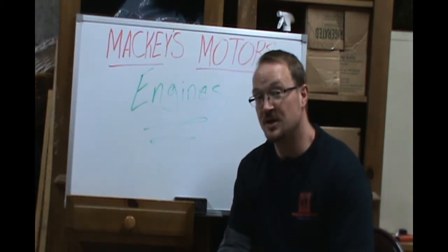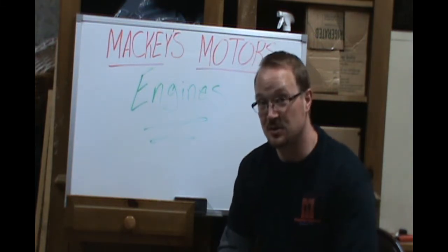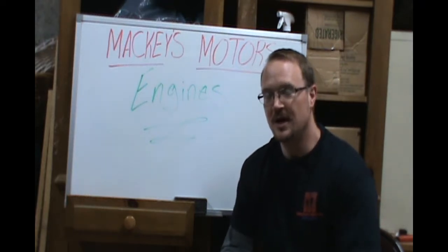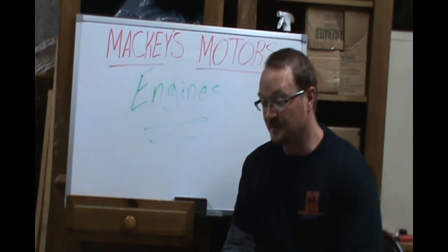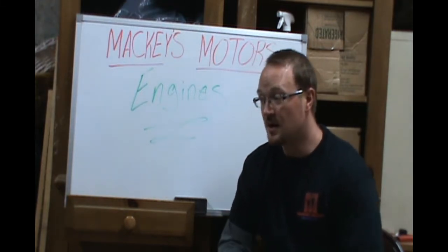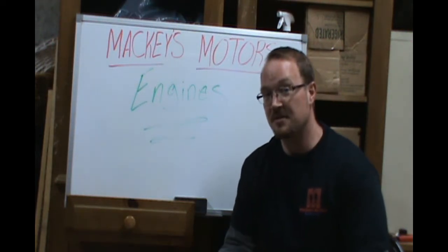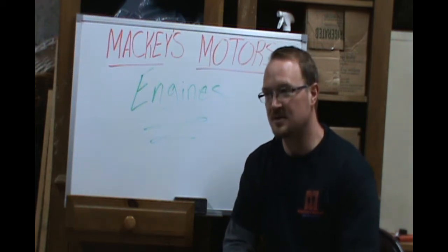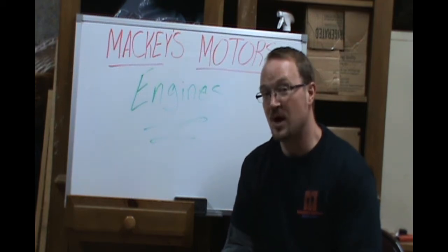Well, every single engine needs fuel and air to operate. So how do we get fuel and air into the engine? Well, you need a fuel system and you need an ignition system to ignite the fuel and compressed air once the cylinders are reaching top dead center. So how do we get to that point? Well, it's really simple. Facts of physics, very basic science, and facts of math, mathematical equations, because without physics and math, no engine would run. We need to have a specific portion of fuel per air, and we need a specific amount of pressure inside each cylinder in order for the combustion to happen.